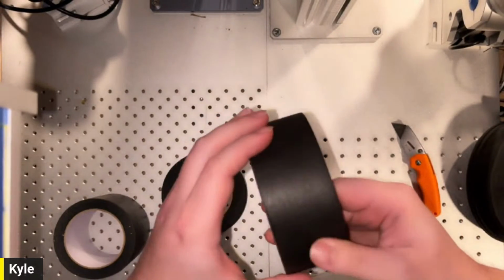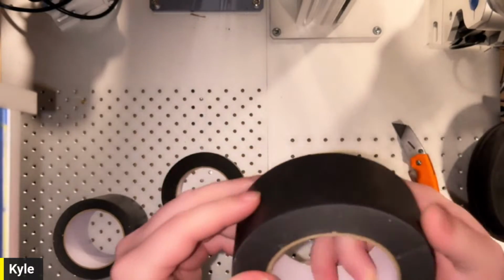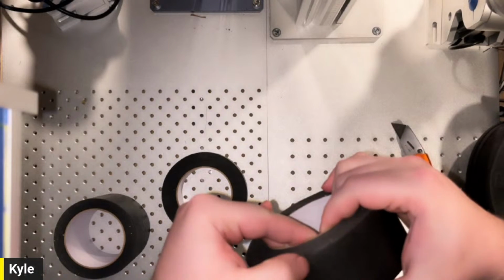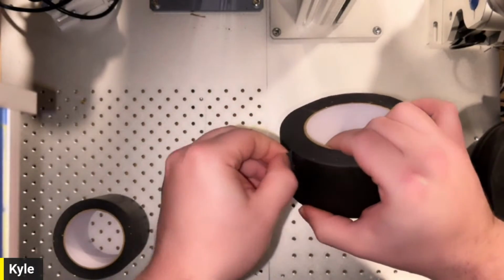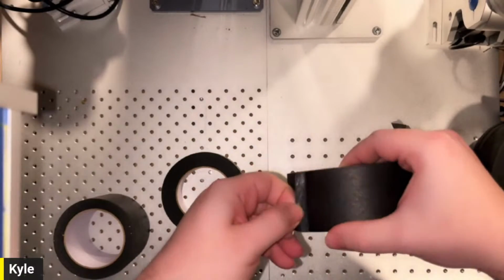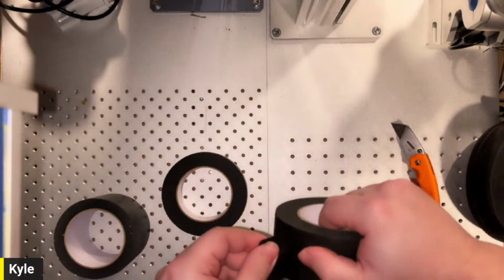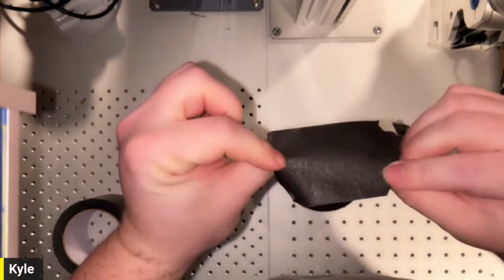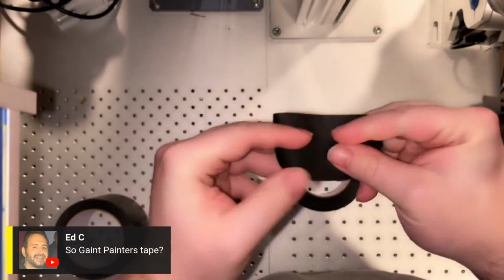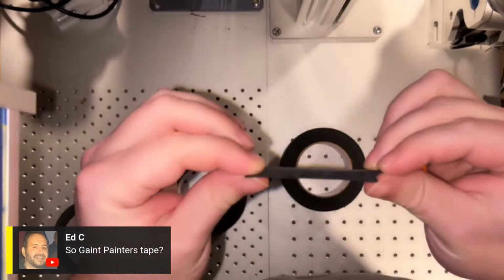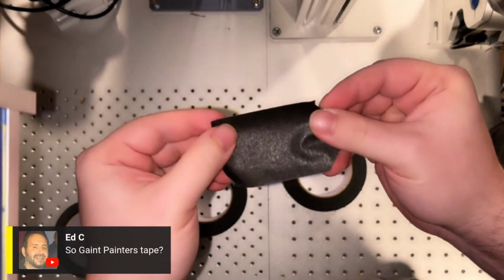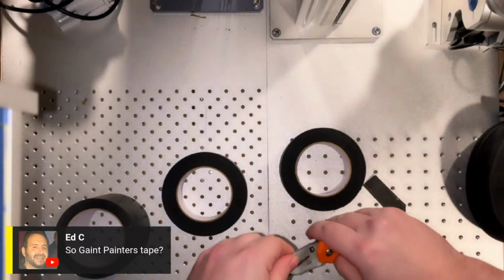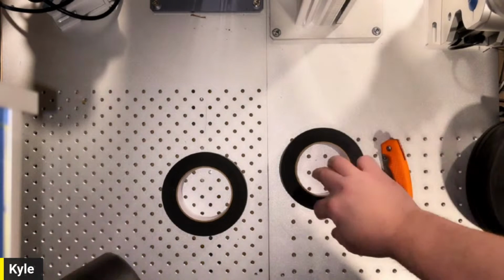Yeah, a lot of duct tapes are PVC backed, by the way. Which obviously is not good. You guys have all been here enough to know that we shouldn't be cutting polyvinyl chloride. So not something you really want to put underneath your laser. Typically, laser tape like this is going to be like a crepe paper backing. So it's really, really thin. It's giant painter's tape. So you've got that paper backing, and you don't need to worry about those nasty byproducts from cutting or marking the PVC.